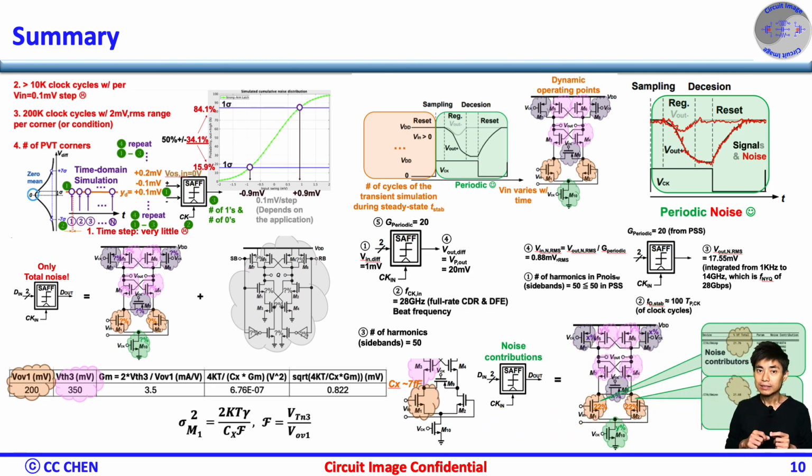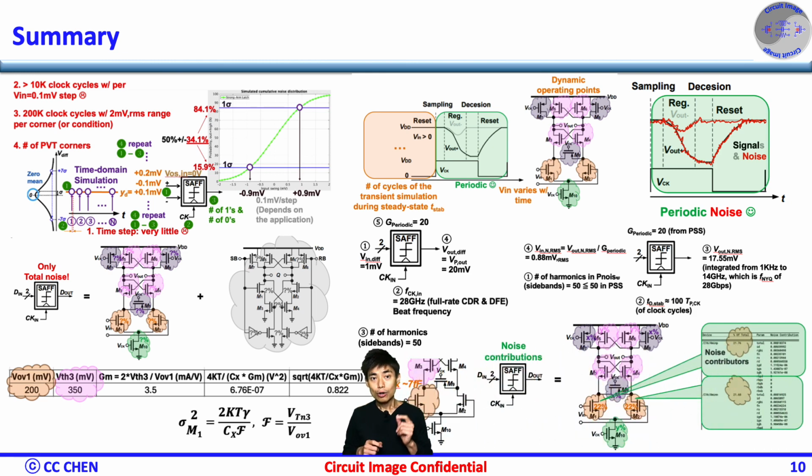Once identifying the main noise source, the designer can also apply a quick hand calculation intuitively before running the simulation, without blind sizing. So both the PSS plus Pnoise and hand calculation from a simple model would be beneficial in the design phase.